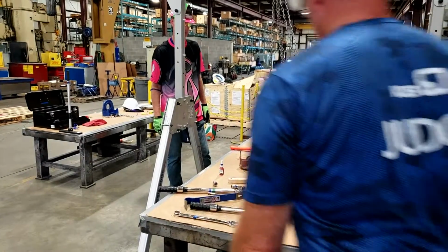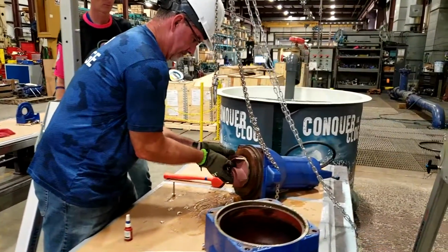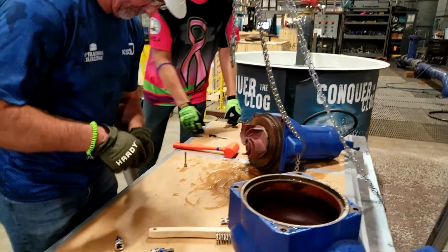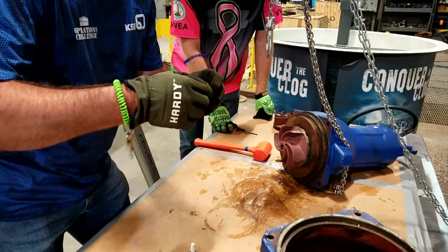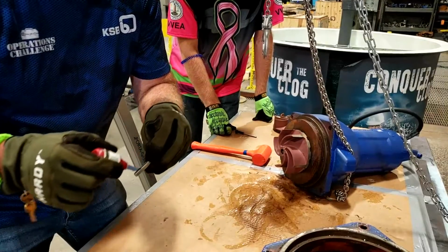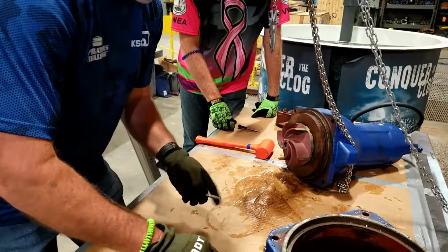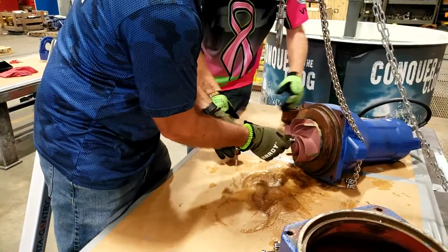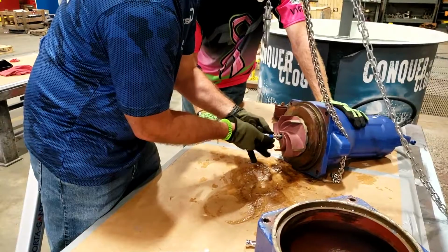You will then install the new F-Max impeller and a new 6mm hex socket bolt and washer and torque to 20 foot-pounds. You will use Loctite on the impeller bolt prior to inserting the bolt. You will squeeze the Loctite onto the bolt. You will communicate out loud, "Loctite applied to impeller bolt."